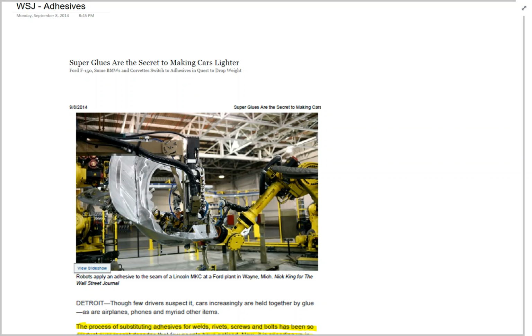Think from a structural standpoint. What do rivets need? A hole, right? What does a hole do? It potentially creates a stress riser, and so if you've got a structure with a bunch of holes in it that is subject to loading, which is cyclical loading, which most things are, especially in an airplane, it's likely that if you're going to get a crack, it will start at a hole, and we'll talk about that more in fatigue.